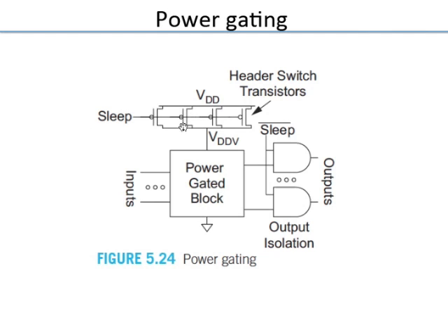Now the question is, what about these transistors themselves? Will they not have power loss? Of course, yes, because even though these are off, they are still in the path and VDD is there. So there are a couple of things. One is, these transistors usually have higher threshold voltage, so the leakage is low. This logic will be low threshold, but these transistors could be higher threshold. Even if they are not higher threshold, because of the series stacking effect, the leakage will be less.